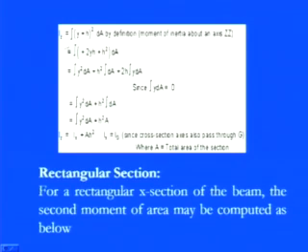So, here we have Iz equal to the integration of (y plus h) squared dA, where dA is the area, because here we are defining the moment of inertia about the axis Z dash, and we know that the moment of inertia about X dash can be easily calculated because it is passing through the centroid. The distance we are assuming is h.